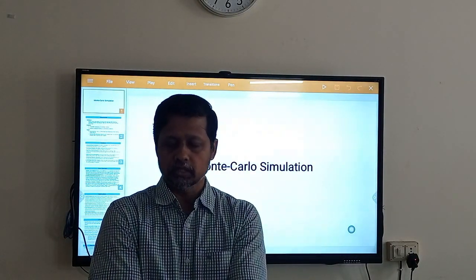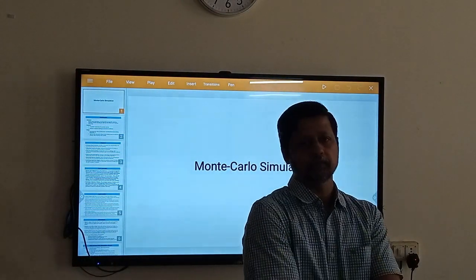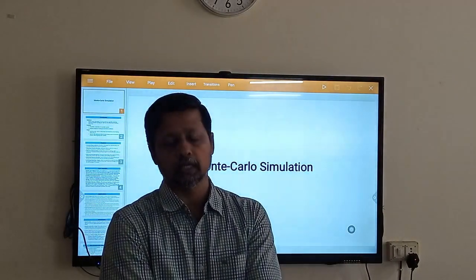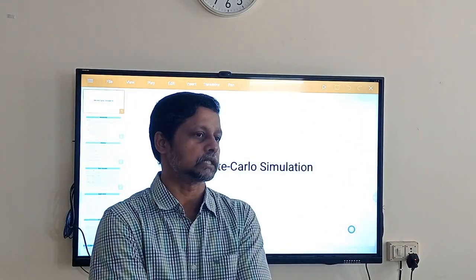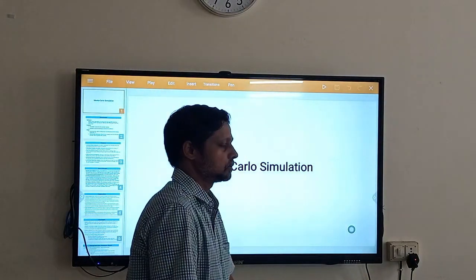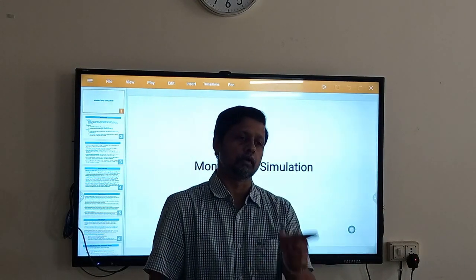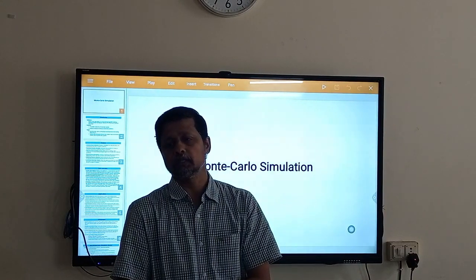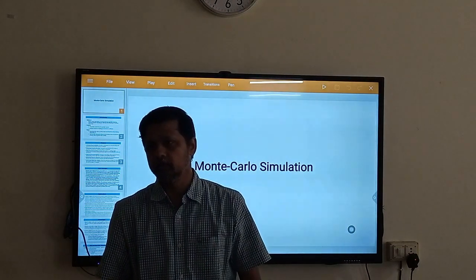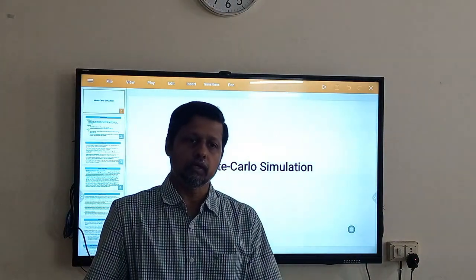Within that particular time period, considering all possible randomness, you will be able to ensure all possible reasons of system failures. Once it is done, whether you are in operation or in design phase, it is equally important. Whether you already ensure that, okay, in my case fault avoidance technique may not be enough to ensure 100% or nearly 100% availability of a system. So in that case you move to fault tolerance technique. When you apply the fault tolerance technique, it will again help you to identify those places where you need to put a redundancy or standby. Okay? Even you have to introduce that.